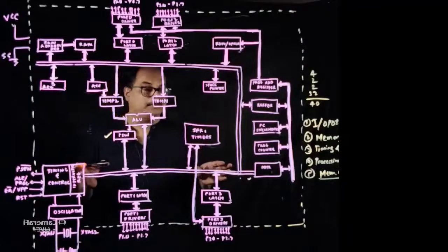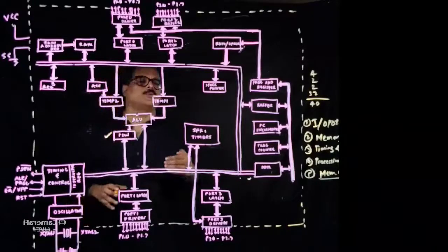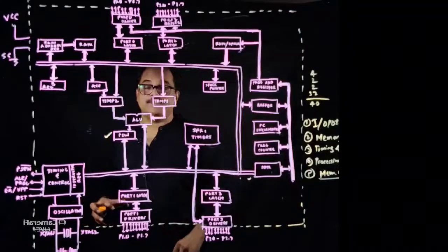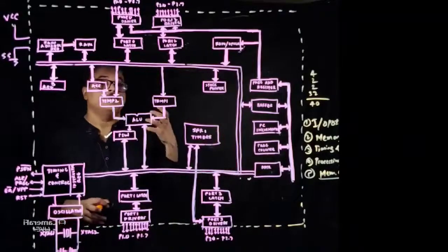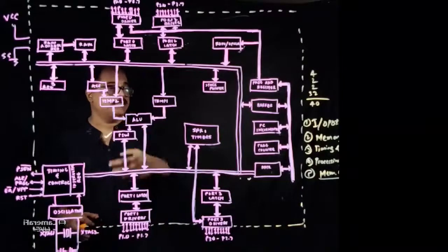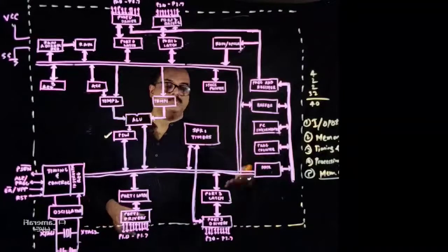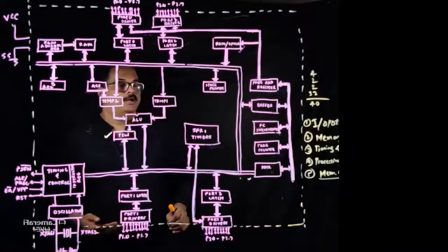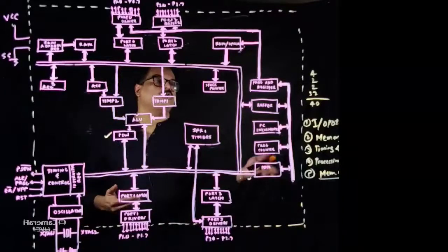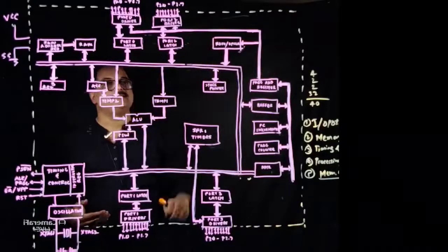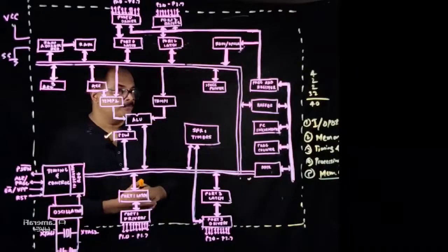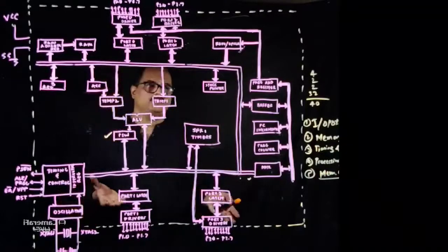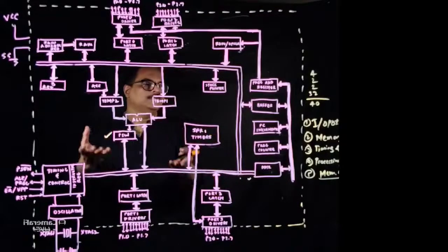We say that a program counter keeps track of the program. That means it is that register which is responsible to tell the microcontroller from where the next instruction has to be fetched and executed. Obviously it should go on incrementing, so you require incrementing circuitry for that. Accordingly, the program address register then helps to access the ROM. Then you have a buffer, like we already discussed in the buffer circuitry. It is used for changing the signal level that we have seen.